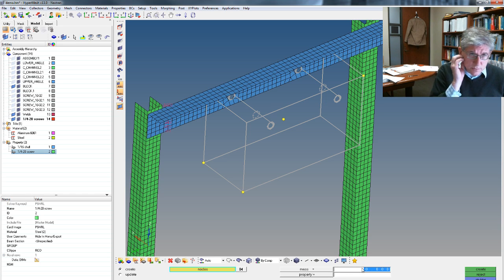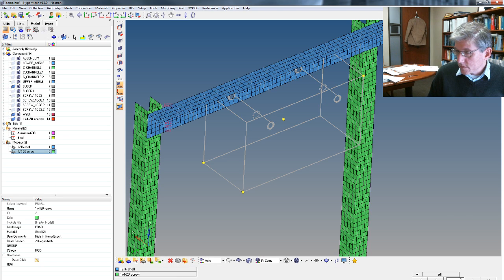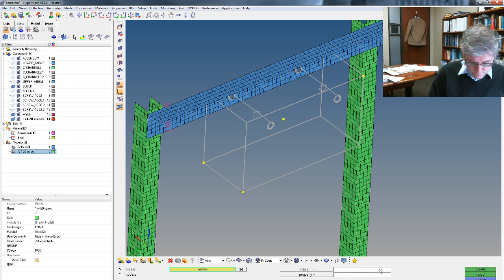So we can put in the mass here, which is going to be the 0.37 divided by 386. Again, I don't know what that is. Figure that out. So that is 0.000958. Whoops. Wait, return. Okay, so that's actually the mass of the electronics package in slinches, and it is going to be right there. Let's pick that node and create. Okay, and there is the concentrated mass.